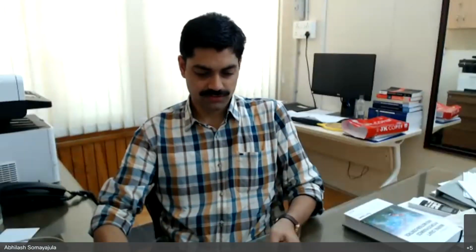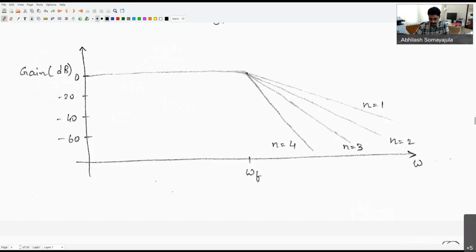All right. So in the last class, we were looking at low-pass filters, and we were discussing the idea that we can try to fix our filter's frequency, the so-called cutoff frequency, at a point such that we are able to separate out the wave frequency components and the low frequency components. And we are looking at how we can do this using first order filters. The main idea here was that we choose this cutoff frequency in such a way that we can eliminate all the wave frequencies to the right of it.